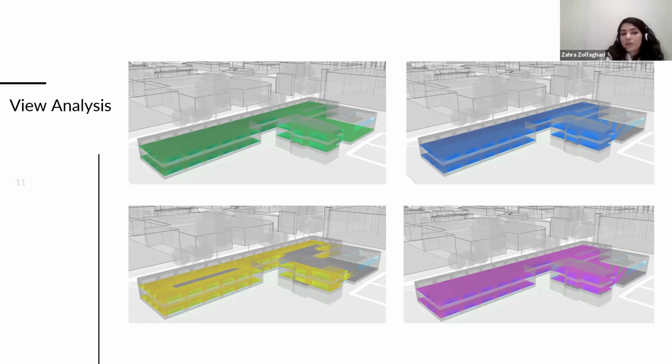So this can also be a financial incentive for developers to optimize for both view and daylight. cove.tool provides 4 types of views analysis based on LEED criteria, including total quality view, 90-degree sidelines, sky and context, and obstructed views. We just ran all these analyses and improved the geometry to get good scores for each of the view analyses.